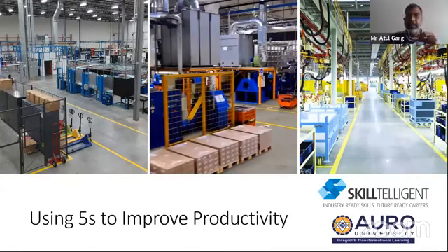Having an organized workplace that utilizes visual cues to maintain itself also allows JIT manufacturing to proceed more smoothly. In this type of environment, it is easier to see problems and move materials efficiently. So the 5S methodology is a basic foundational element of lean practices overall.